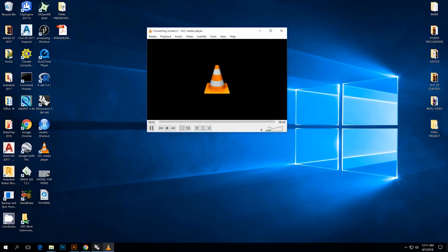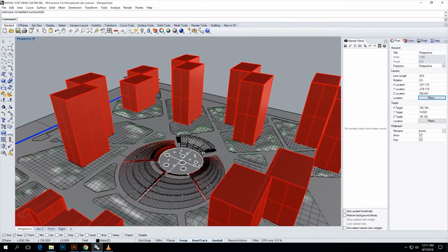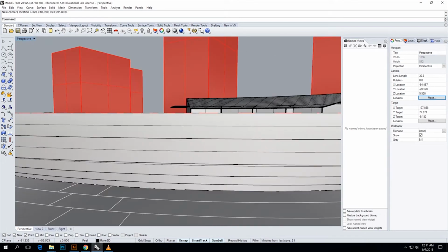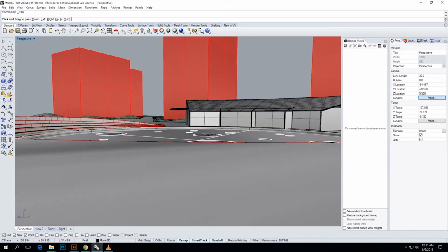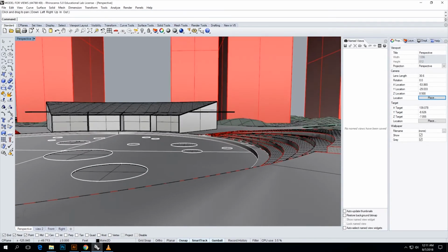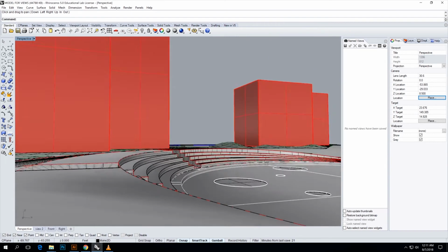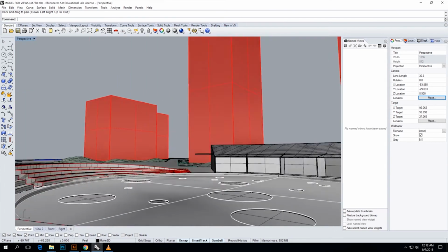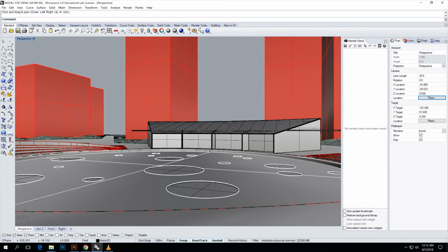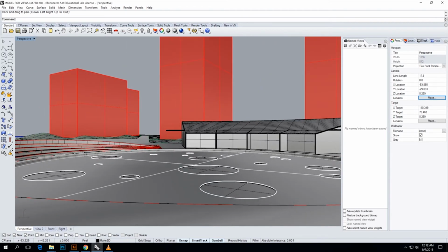In this video tutorial, I'm going to make a landscape view using Rhino, Illustrator, and Photoshop. The first thing we're going to do is define, here in the right panel in camera options, the location. I select place here, and immediately I have an eye view or eye perspective. Then in viewpoint, in projection, I'm going to select 2-point perspective. In this way we can straighten the vertical lines of the model.